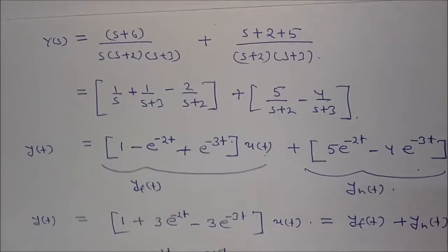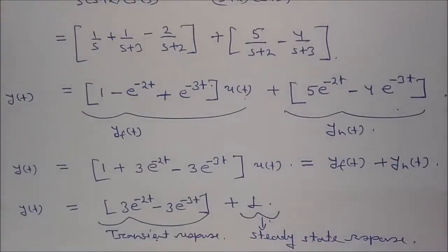See in this equation what you have got. Natural response is always contributed by the initial conditions only. That means it is entirely independent of the external applied input, and it is always temporary in nature.